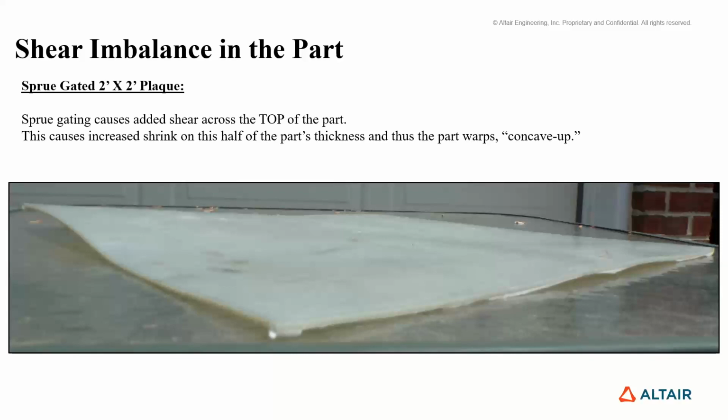But this potato chipping is happening because I'm getting so much shrink. I'm so far frozen around the outside edges, and I get so much shrink in the middle that I set up this kind of anisotropy from the center outward. I set up orientation with the molecules, molecular orientation, and I have a lot of shrink just thermally going on as this goes.